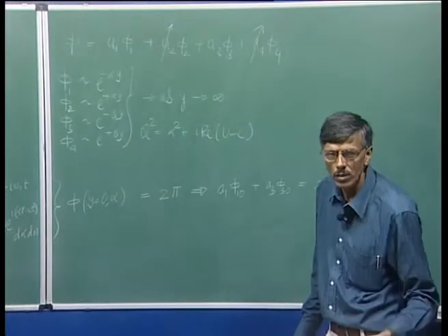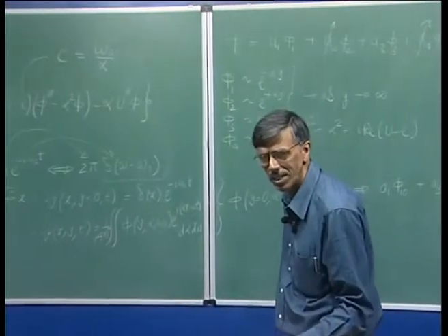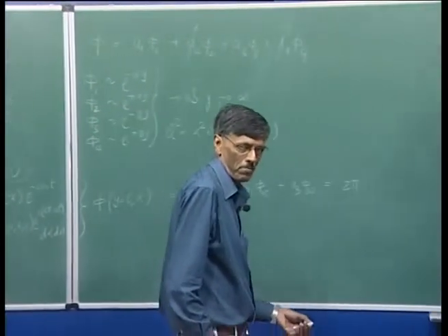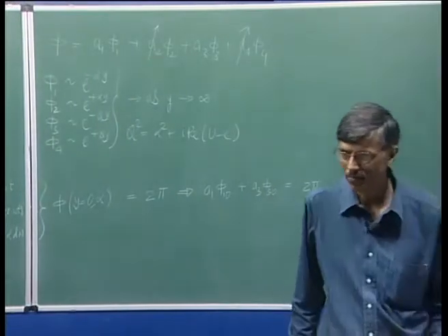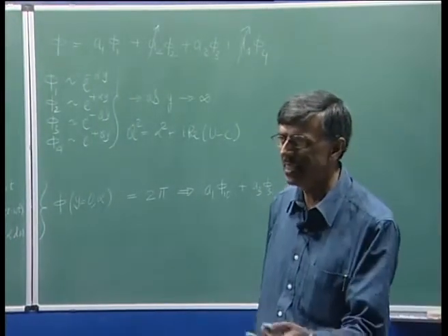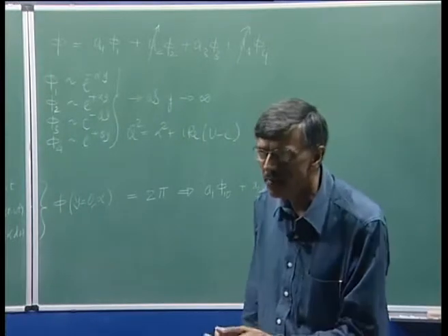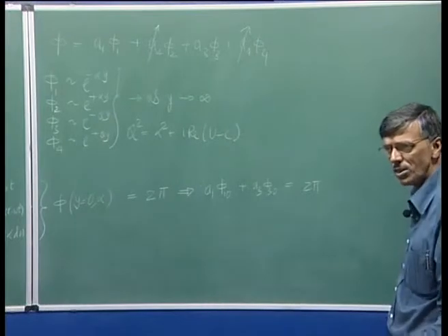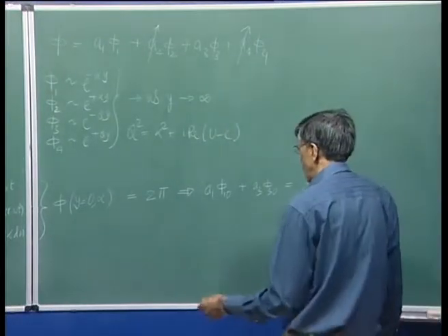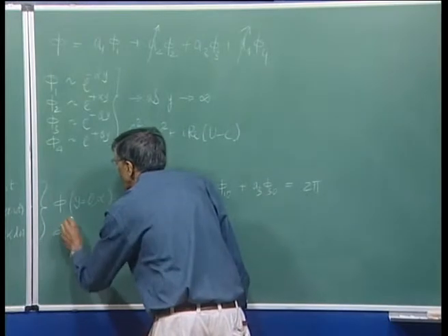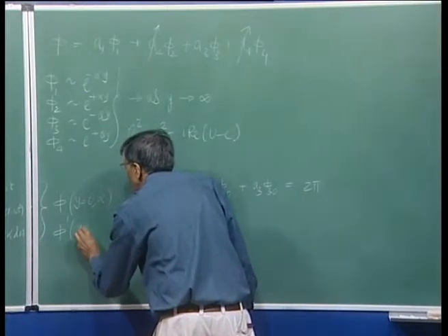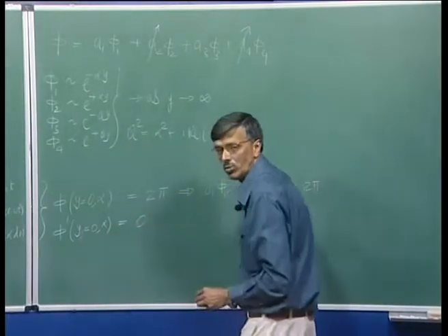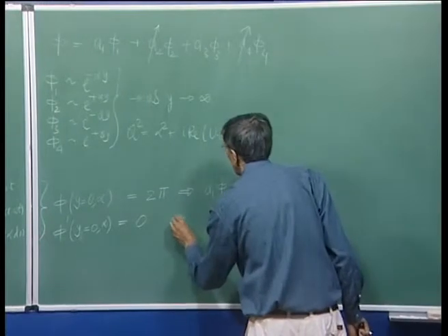What is u? If you recall, the mass conservation equation gives us what? The mass conservation equation, we did get that i alpha f is equal to phi prime, right. So, if f is equal to 0, then phi prime has to be equal to 0, right. So, that you have done. So, basically we need to also have phi prime at y equal to 0 for all alpha identically equal to 0, and this gives you this.